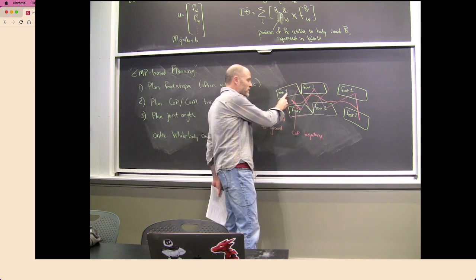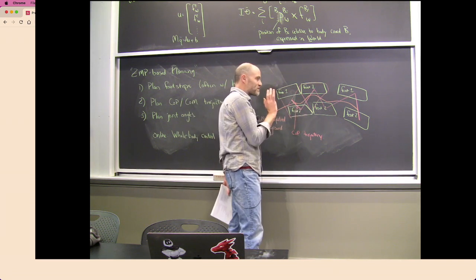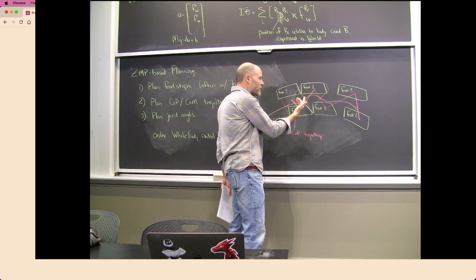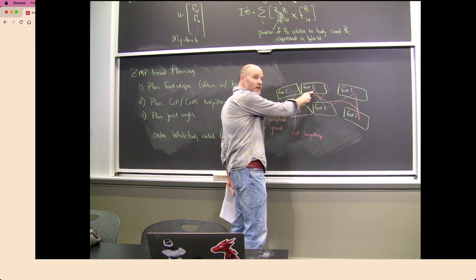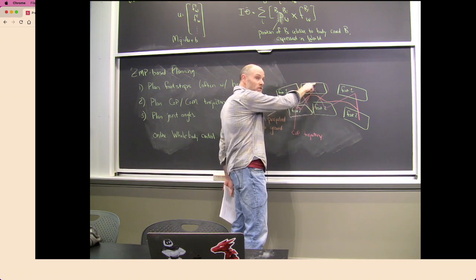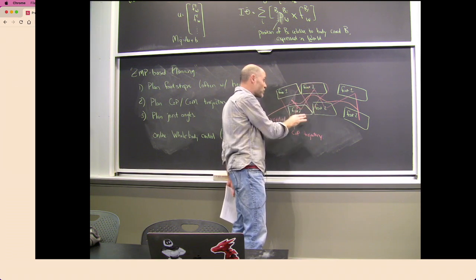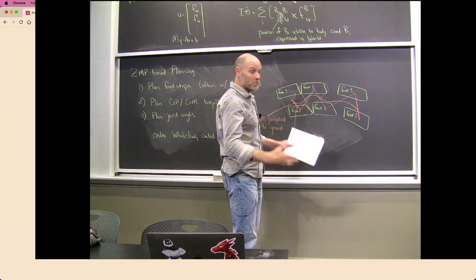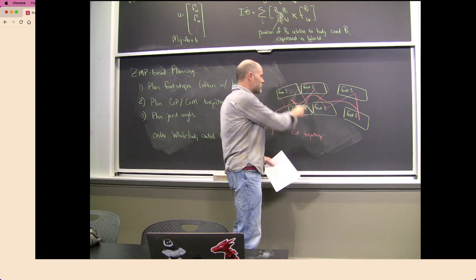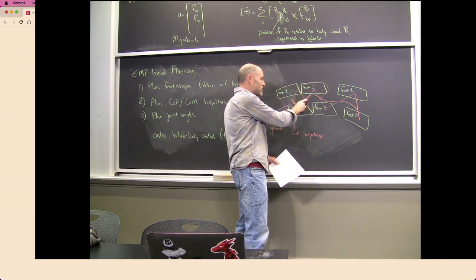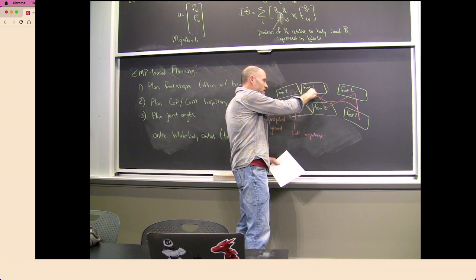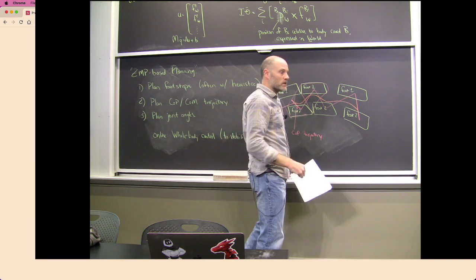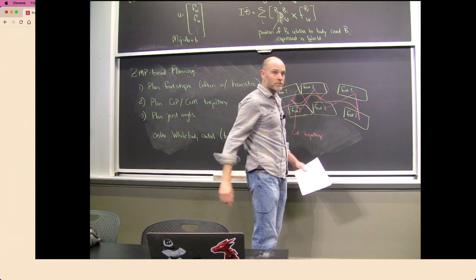So what happens in the running case? If I lift off, then my center of pressure is not defined for a moment, and then I come back. What I want to do is catch it in a place close enough inside my foot that I can apply any stabilization I need. If you were exactly on plan when you jumped, then you're fine. But imagine your model was a little bit wrong and you landed a little bit off. Your center of mass is a little bit off from where you expected it to be. Then if your center of pressure was planned to be in the center of the foot, you'll have enough time to react and get back on track before your next jump.